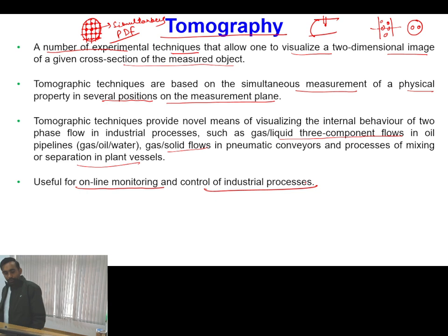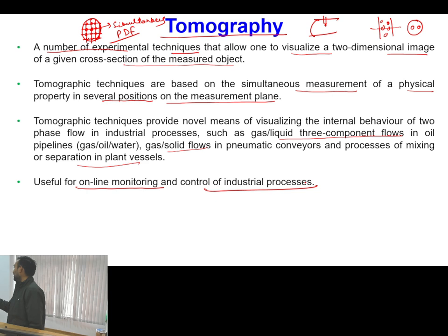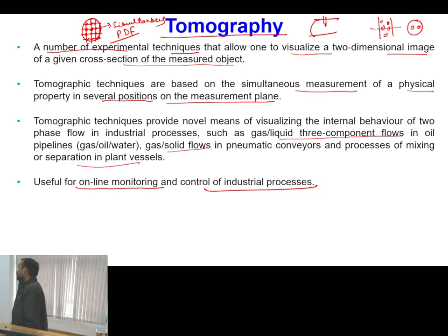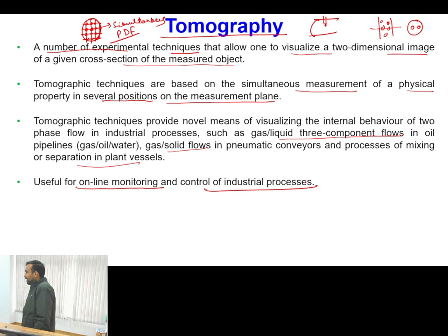So it is not feasible that at some point of time we take a sample of the measurement, then stop the plant, correct the problem, and then start again. What we have to do is, while the process is running, put a large number of measurement instruments at several desired locations, and by doing online monitoring take the corrective measures. Is this point clear?